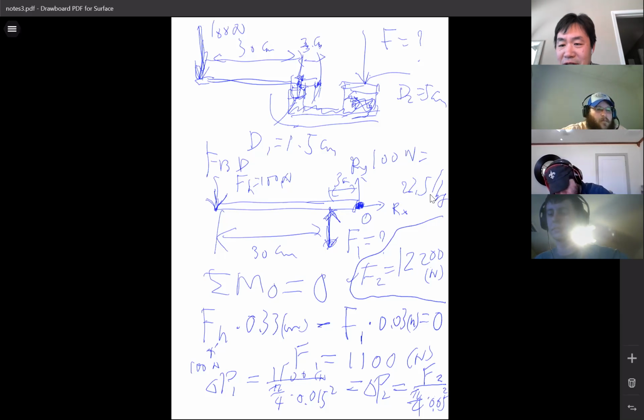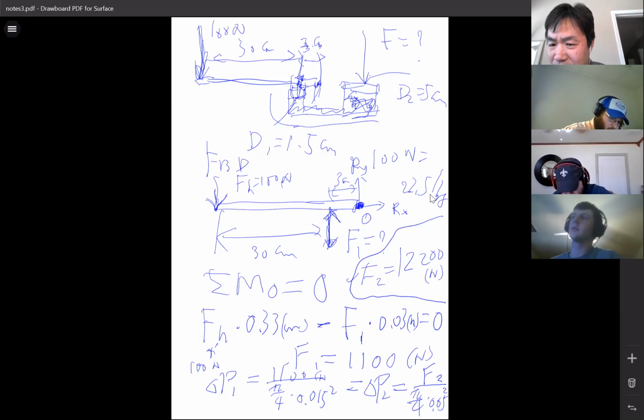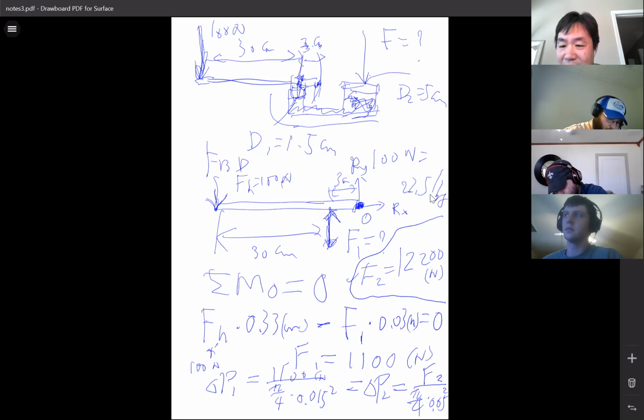But be careful: the sentence I just said is that everywhere will feel the same added pressure. I never said everywhere has the same pressure. Those are two different meanings. In the fluid, of course, everywhere has different pressures because of different elevations. But that added pressure, delta P, will be felt everywhere, no matter whether your initial location has high or low pressure.